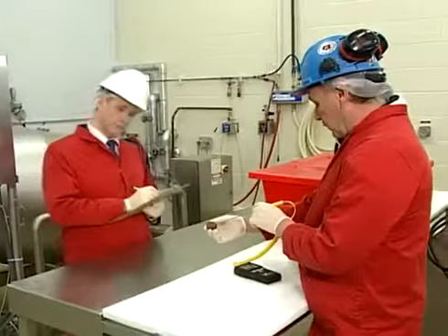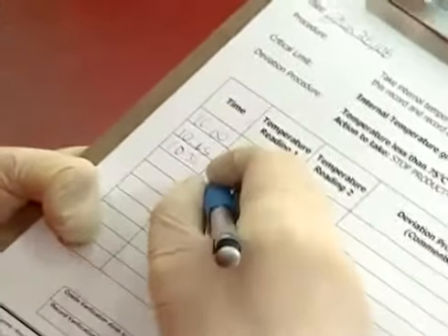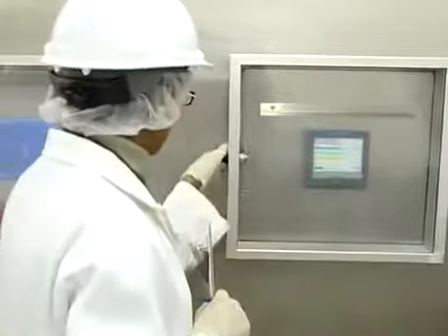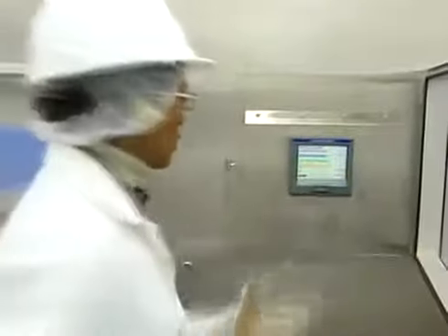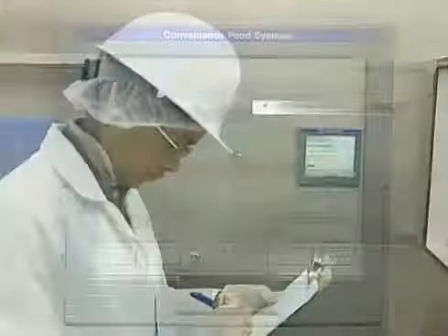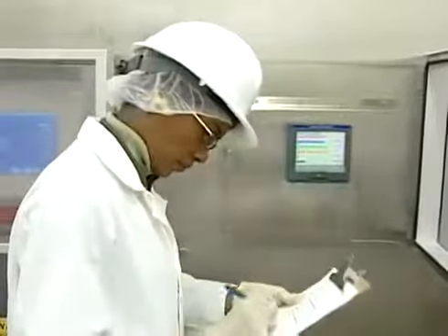Critical limits are set to ensure control of health hazards. They can be based on government regulations, industry standards, company standards, and scientific data. Make the criteria understandable and to the point, so there's no confusion among employees. Displaying the critical limits next to the critical control points is an excellent way to help employees identify when the process is out of control. This is usually done by detailing the critical limit on the CCP monitoring record.